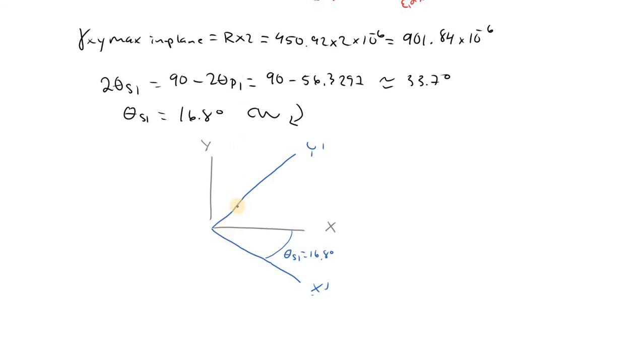This time around, the object will look slightly different because our shear strain causes the angle inside here to change. A positive shear strain causes this angle to be smaller. At the moment it's 90, but if it's negative, it will cause the angle to become wider. Just keep that in mind.